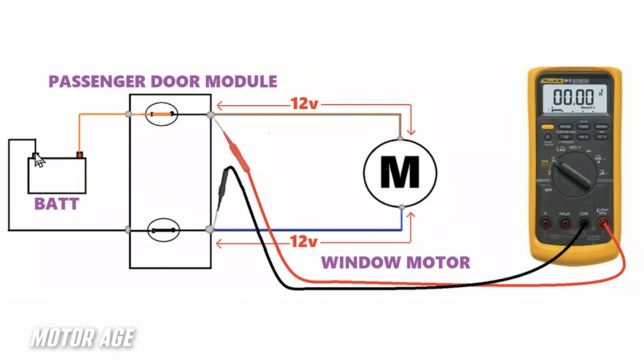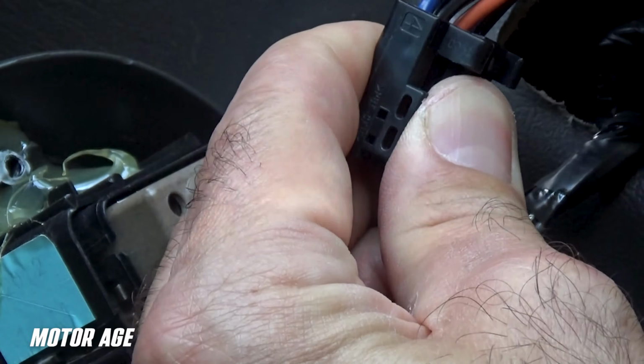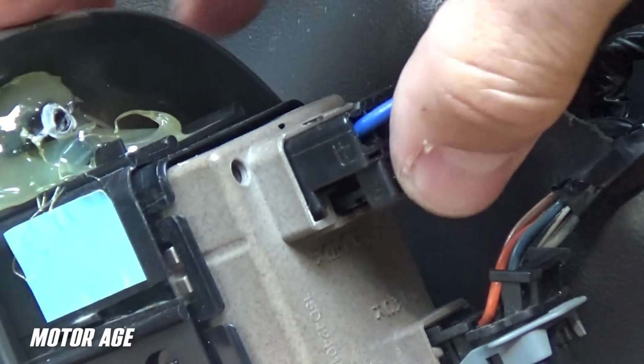We found a dislodged terminal that was not properly secured in the connector housing. And upon further inspection, we found the spread terminal. We repaired the connector properly. Now it's time to reinstall it and verify the fix. Well, that was fun.